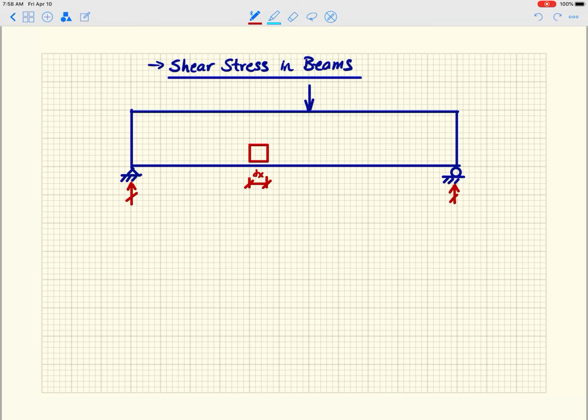And so what we have necessarily is a shear that develops, and we're going to call this tau xy, right? Shear is sometimes referred to as sigma, like our other stresses, but in many cases, particularly in your textbook, I believe they call it tau. So you think about it as the same as sigma.